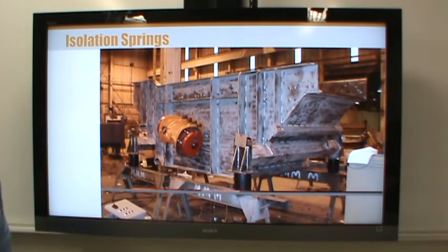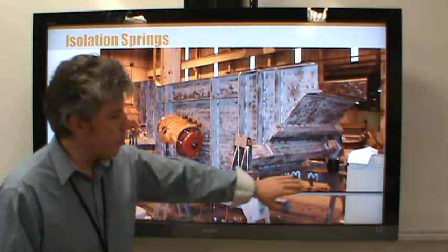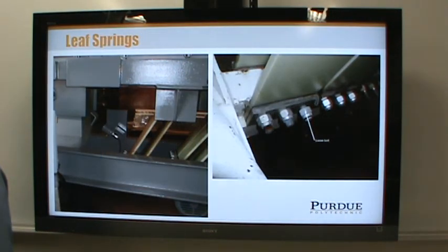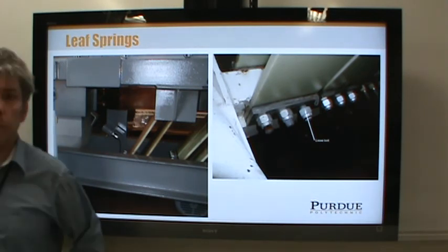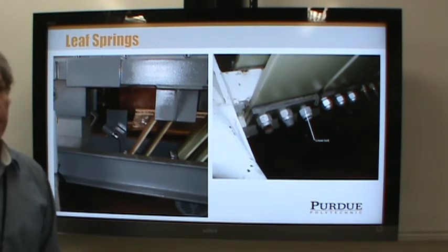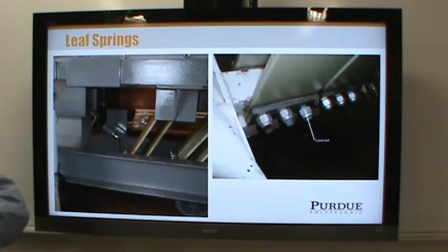And here's a place where no mechanical springs are being used. There are just isolation dampers. So these are supposed to lose energy on purpose. They're supposed to convert some of the vibrational motion into thermal energy. They can also use those to electrically isolate. Electrical isolation is another big reason. Yep, you're right. On the other hand, if you have a static problem, then you have to ground the machine.